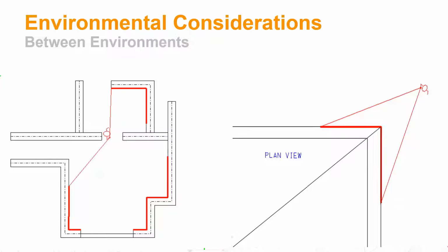The same thing applies if you are scanning outdoors or walking around the building, like in the right picture. If you reach the edge, again, maybe pause for a second. You can sort of paint the building by moving the system slowly up and down, so you allow enough time to see the features on the right and on the left-hand side of the building.